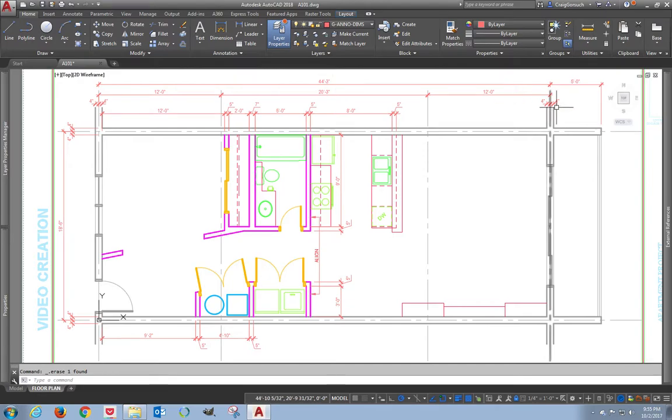Well, that's obviously going to throw this dimension off, and that would be a prompting for a revision to the documents from the contractor. So by leaving these dimensions out, if these overall conditions are wrong, or if something happens while they're building it and they kind of creep things around a little bit and don't put things in the exact right spot, we don't have an exact perfect dimension that's going to lock them into something that will accidentally give them a conflict. But I wanted to point out that what I have shown here is almost all the information they would need to locate all these walls.